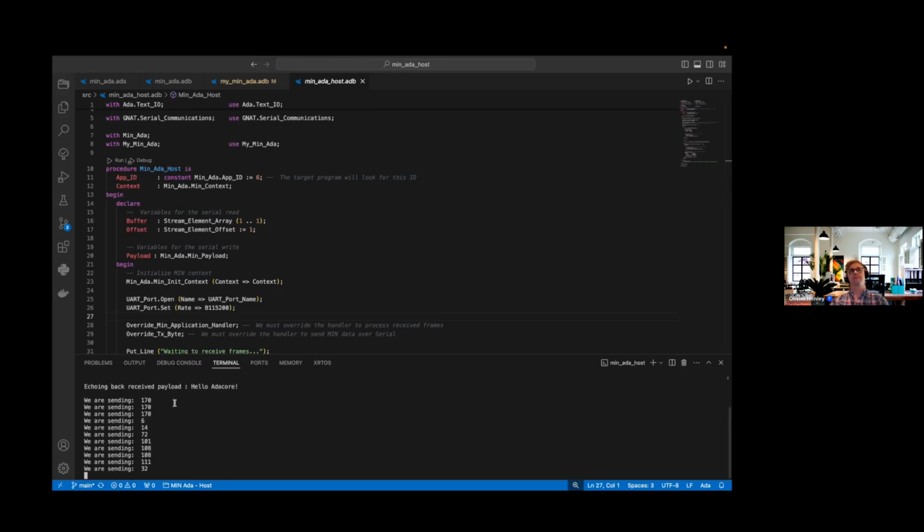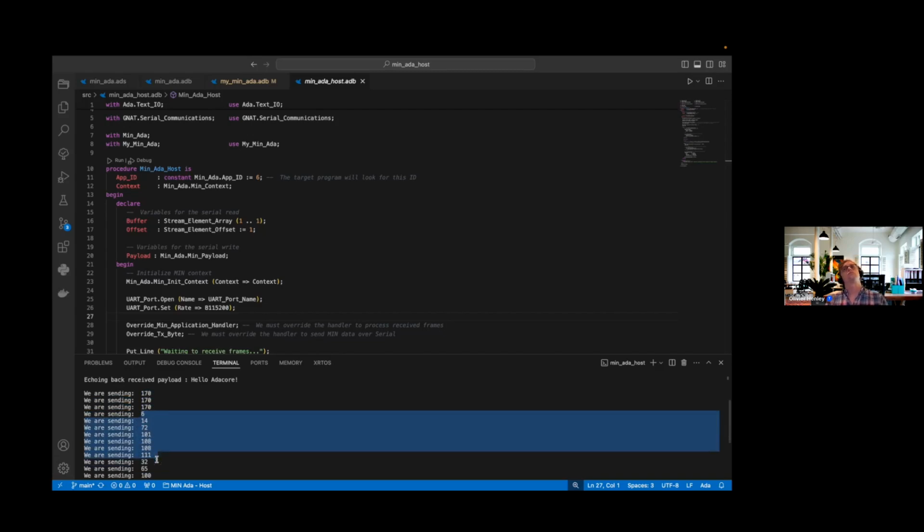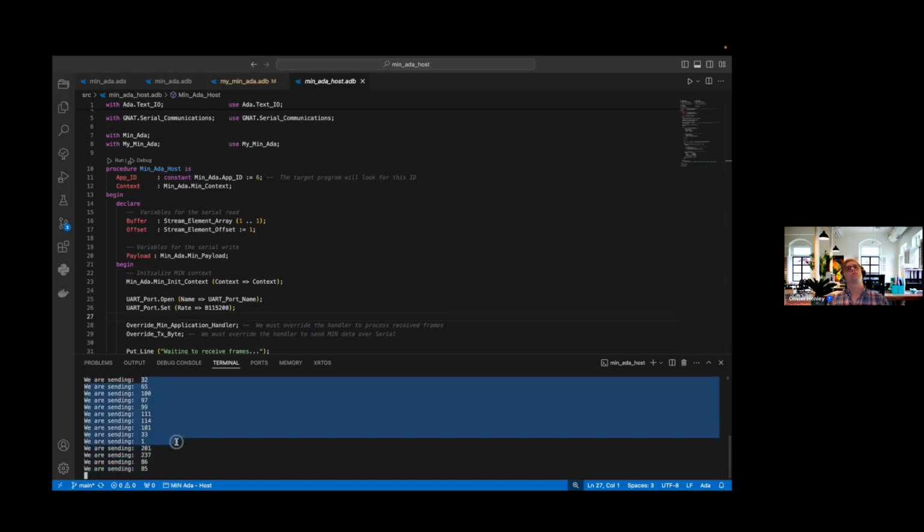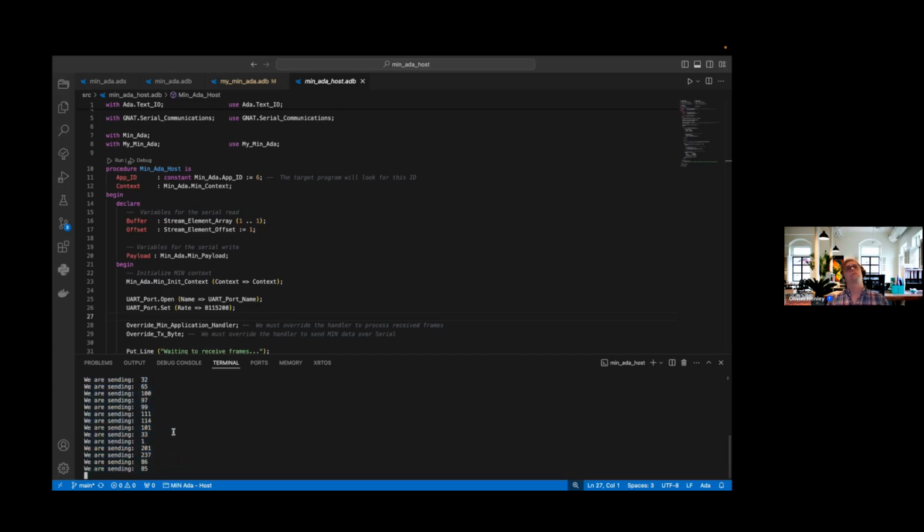And we can see that we received that message, and we even see all the bytes coming in one by one. So this is just for demonstration purposes, of course. I decided to show what bytes we're receiving, but essentially we see these are actually our start bytes. We're sending 3 in this case for redundancy, but these are the special start bytes, and then we have some additional metadata about what's being sent, and we also have the payload here, which is the actual message itself, and then finally we end with this special end byte that tells us that the frame is completed.